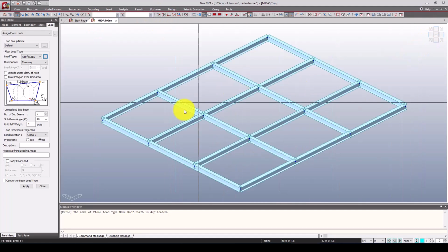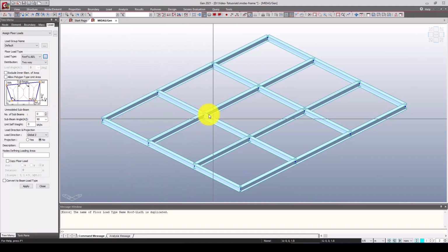and here the command is called active. It will just show the selected active file. Now actually this slab is a two-way slab. Now I want to use the two-way, and you also have another option in case it's one way, you also apply. Now here is defining the load area, and it's called copy floor load to the upper load. So the distance from one is 3.4, and here I actually want Z copy or populate to the upper stories.